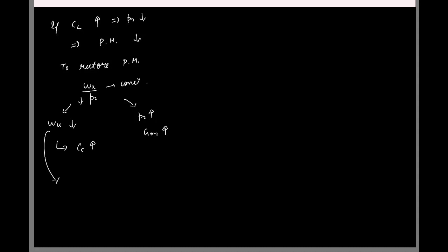If I just increase bias current, all the operating point voltages will change, right? I don't want to make a lot of changes. I don't want to change the operating point condition and increase GM. I want to keep VGS minus VTH the same and GM must increase. What will you do? If you only increase W by L, again things will change, right?